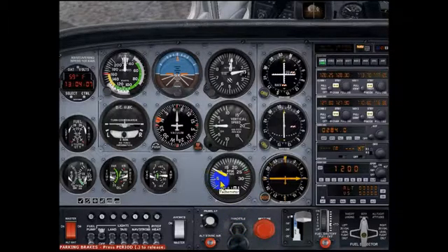That's where we want to be at. So after starting the engine, the first thing we want to look at is our oil pressure. All right, so our pressure is not up. Just turn that fuel pump on.